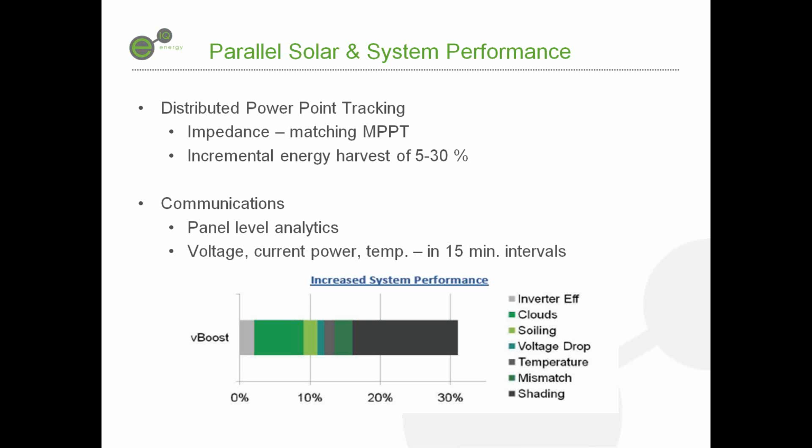But nonetheless, it's always something that's going to generate a lot more mismatch than what's there on a pure sunny day. And that's power that we get back. In certain cases, it could be as much as 7%. Soiling, the same thing as cloud effect. Soiling rarely happens uniformly throughout the array. And if that soiling happens in any way that starts to generate mismatch, we're going to mitigate that effect. And that's also worth a couple points on most systems.